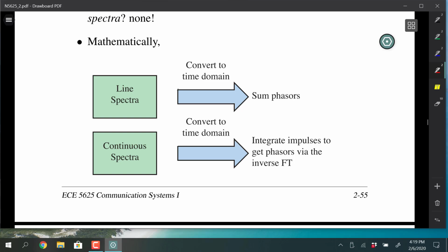It takes a signal, suppose it's a 10 megahertz sinusoid, and how does it display that on the spectrum analyzer? So the spectrum analyzer has a sweep generator running, sweeping over a range of frequencies, and then that sweep generator is producing a sinusoid that's mixing the signal or multiplying the signal with the input signal.